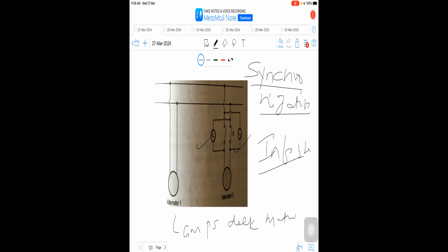Whenever there are two voltages in exact phase opposition, the angle between them is 180 degrees, and then the resultant EMF ER becomes 0. At that time, if the switch is not closed at that particular instant, the voltage across the lamp will go on rising, and the synchronization will not be proper. The alternate darkness and brightness of the lamp will not indicate whether the incoming alternator is running fast or slow.